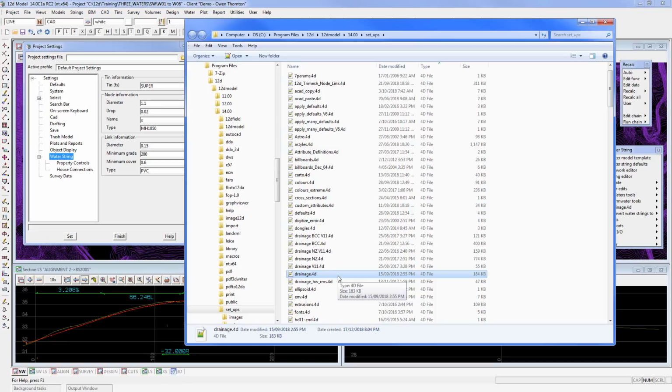But in this series, I'm presenting this design based on the QDM guidelines, the Queensland Urban Drainage Manual, and I would like to instead use this one, Drainage BCC, which uses the pit types that are widely used in Queensland, that are based on the Brisbane City Council drawing set, also very similar to, they're all the same pits that are used by TMR and specified in the IPWEAQ drawing set as well. But they're all published by Brisbane City Council along with the inlet capacity curve, so that's why they get the moniker BCC there. But they are widely applicable throughout all of the state of Queensland.